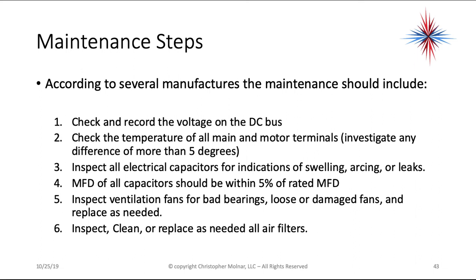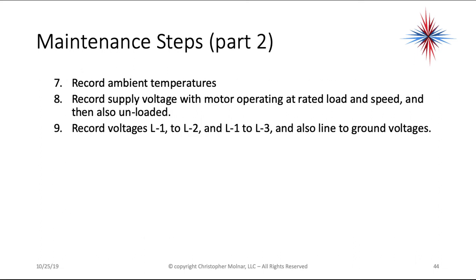Inspect all electrical capacitors for indication of swelling, arcing, or leaks. The microfarads of all capacitors need to be tested and should be within 5% of the rated microfarad. Remember to isolate components and only test capacitors after they have been discharged. Inspect ventilation fans for bad bearings, loose or damaged fans, and replace as needed. Inspect, clean, or replace as needed all air filters.